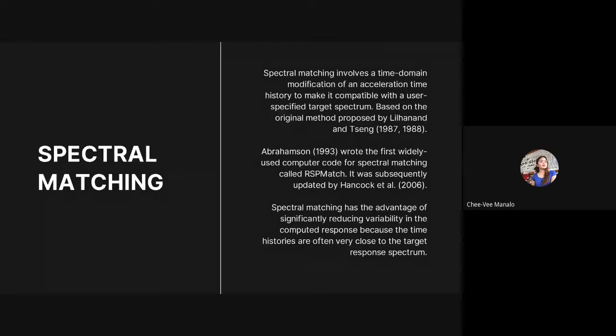In 1993, an engineer in seismology wrote the first response spectrum matching for earthquake accelerograms, to match a specific target response spectrum using the wavelet algorithm proposed by Abrahamson. It was subsequently updated by Hancock in 2006, a little more stable and faster. Spectral matching has the advantage of significantly reducing variability in the computed response because the time